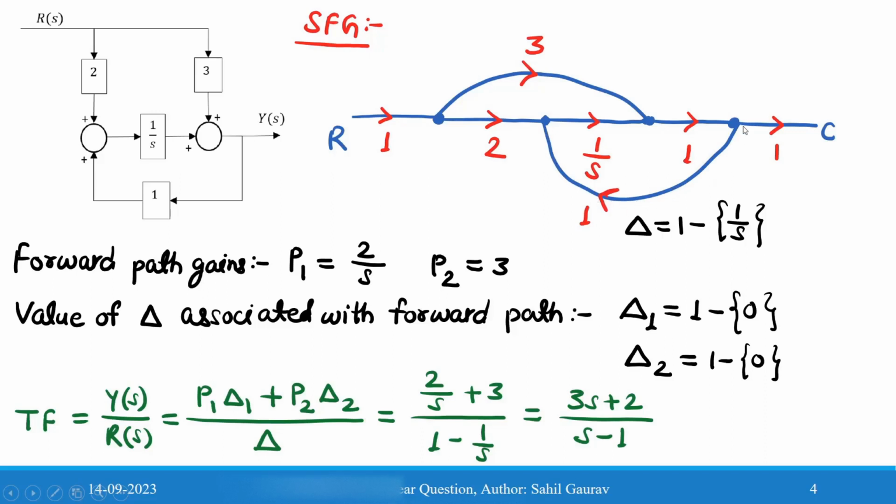So this feedback path having gain 1, we just add it to the summation block. If it were a negative feedback path, then we would represent it here as minus. Now the output from where the feedback is coming, we take as gain 1, and the output we get is Y(s).